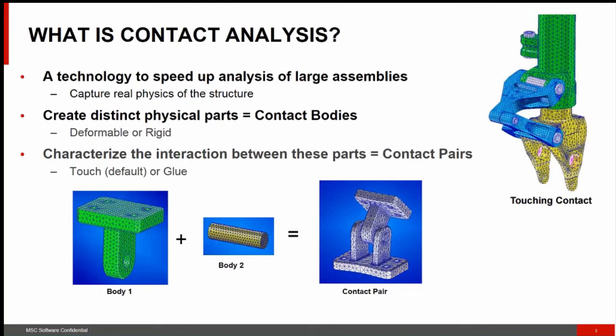And from the model assembly perspective, it's very important to have an integrated structure so the structure doesn't have any rigid body motions and the parts move properly. Many of the parts come from various sources, divisions and departments, and this is a challenge to assemble properly and quickly. This is why the contact procedure can be very useful. This way we can detect the motion of these bodies and parts and easily assemble them without dealing with node to node connections, manually connecting the nodes, or remeshing the parts.